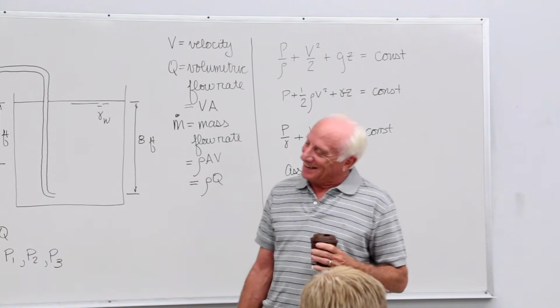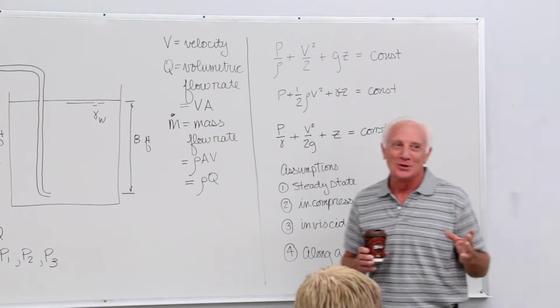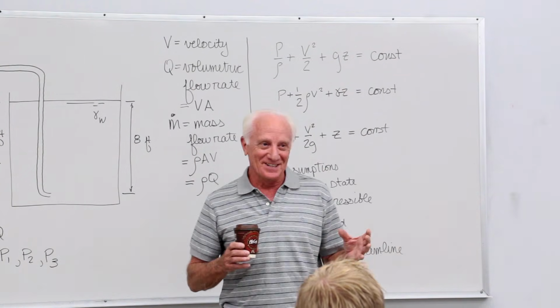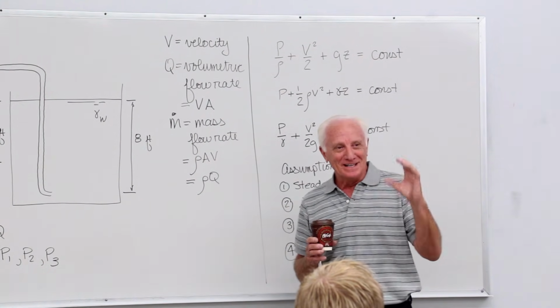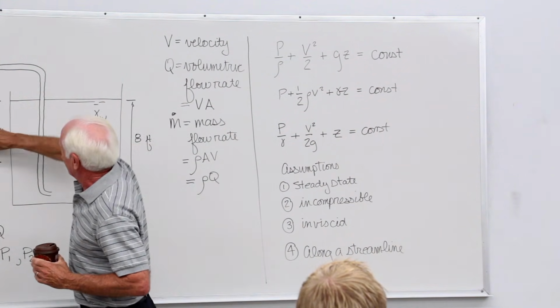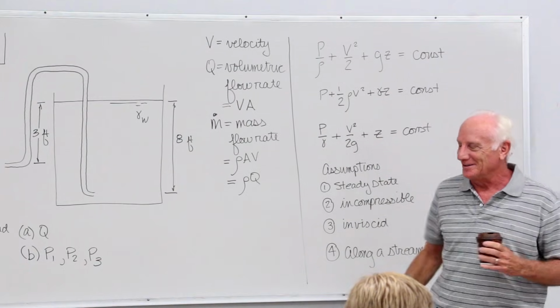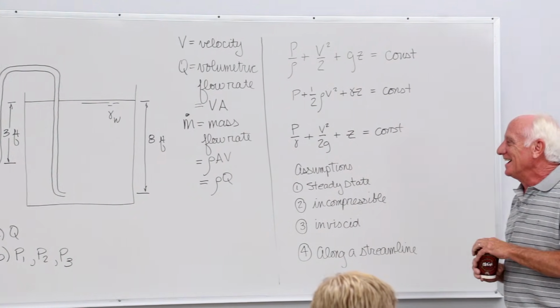Okay, right. Excellent steps. 1, 2, 3. You're exactly right. So you don't just put the tube in there and say water's going to come out of here. It's not going to come out. No, put it all underneath there. Get it full of water. Put your finger over it. Then raise it out of here and put it down below this, and now take your finger off. Voila, fluid comes out. Okay, good, good.